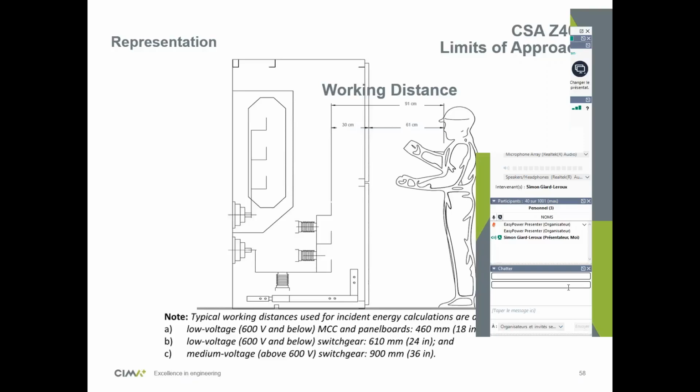So I have another question from Georges Chaquette. For 240/120 volt single phase, do you calculate line to neutral arc flash? For single phase systems, IEEE 1584 is the one that states the method, and the method they recommend is to use the same equations you would use for three-phase networks, but with the line to ground fault current instead. So you can calculate it, but you need to plug it into the formulas.